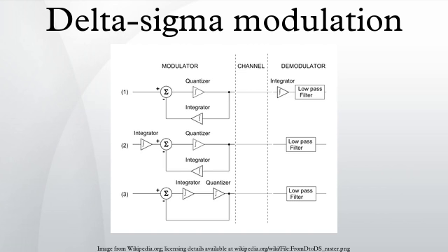Initially, when a sequence starts, the circuit will have an arbitrary state which is dependent on the integral of all previous history. In mathematical terms, this corresponds to the arbitrary integration constant of the indefinite integral. This follows from the fact that at the heart of the method there is an integrator which can have any arbitrary state dependent on previous input. See Fig 1c. From the occurrence of the first pulse onward, the frequency of the pulse stream is proportional to the input voltage to be transformed. A demonstration applet is available online to simulate the whole architecture.